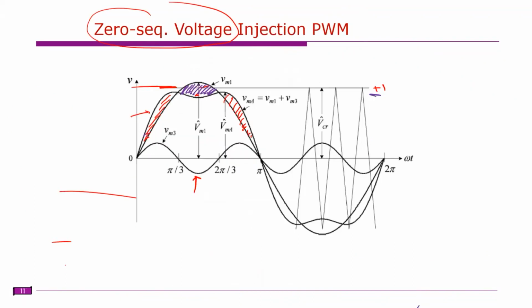The advantage with this zero sequence injection is that lower order harmonics are not injected. The problem with overmodulation is the lower order harmonics, and that problem is solved. Another thing is how much you can inject. Usually this is 10% or 15%.